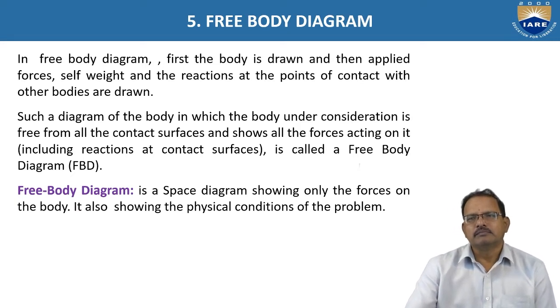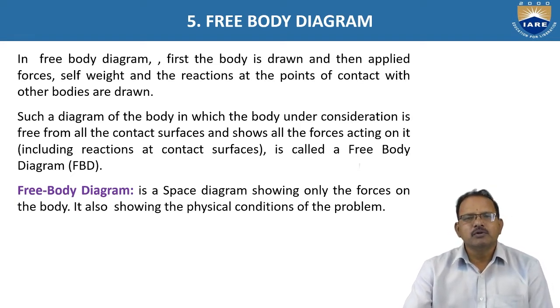Free body diagram. The free body diagram is most important for analyzing the forces which are acting on a body and their effect. This is most important, particularly for students who are interested in settling in structural engineering. In the free body diagram, first the body is drawn, then the applied forces and self-weight are represented, and the reactions at the points of contact with the other bodies are drawn.